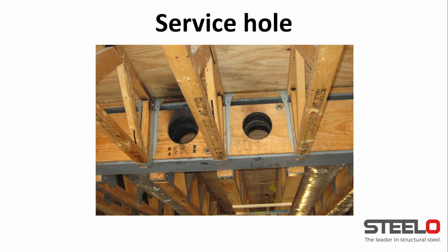A service hole is a normally larger hole in a steel beam. Here on the photo you can see it going not only through a steel beam but also through some timbers. They are normally up to 100 millimeters in diameter, and they should be drilled in the middle of the beam because that is where the stress loads are the smallest.